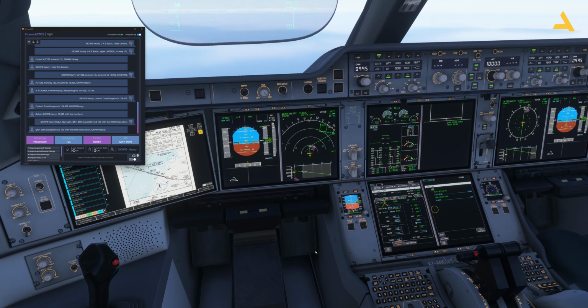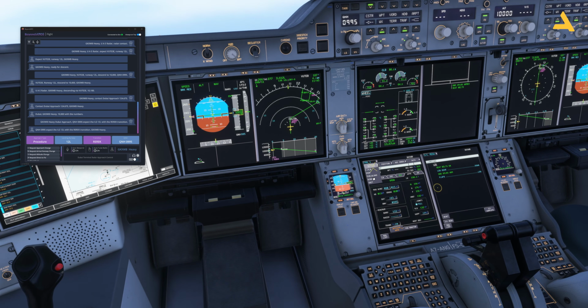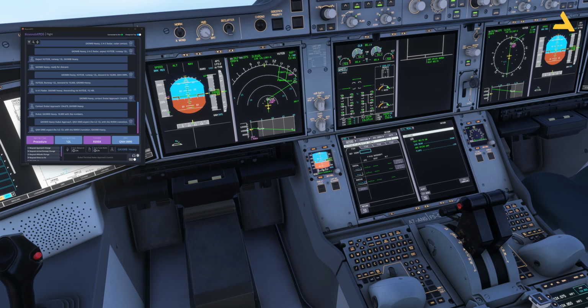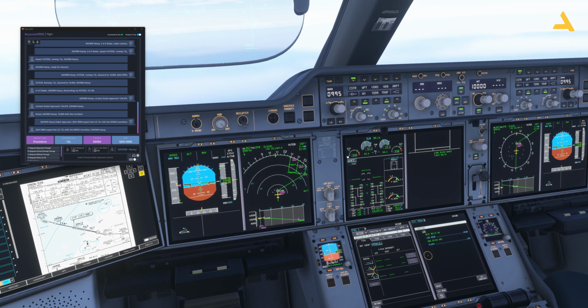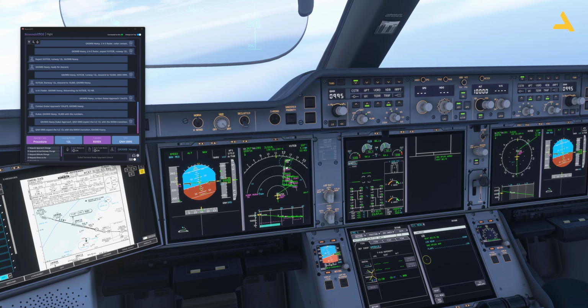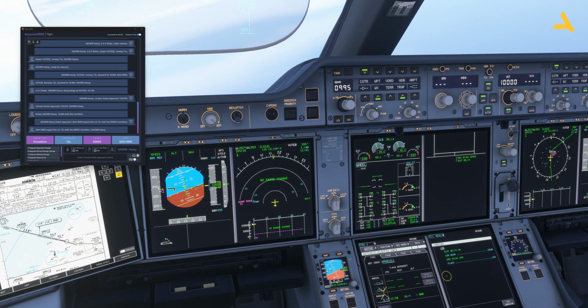Now there is another thing that I can do. If I go to the flight plan, if I click this option, flight plan info, and go to the fix info, I can set a radius for the runway of 6 nautical miles. So if I type it over here, OMDB, you can do it for any of the waypoints or the fixes. 12 left, and if I press enter, I can enter 6 nautical miles over here. So there will be a 6 nautical mile radius over here because I will be lowering the gears at this point. That's it.